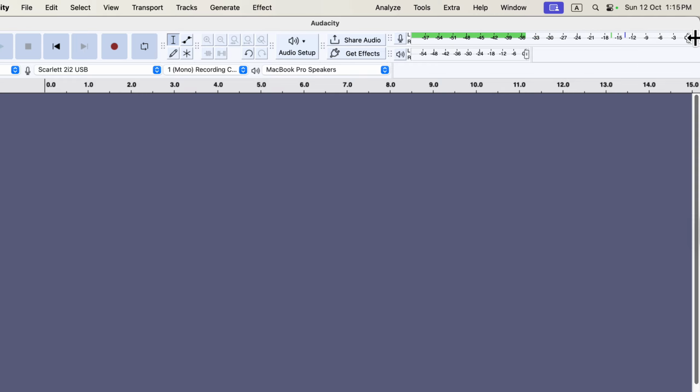While you are talking into the microphone, the levels should be between -18 dB and -6 dB. If your audio levels are in that range, that means you are getting good enough audio signals, and it is easy to process later.